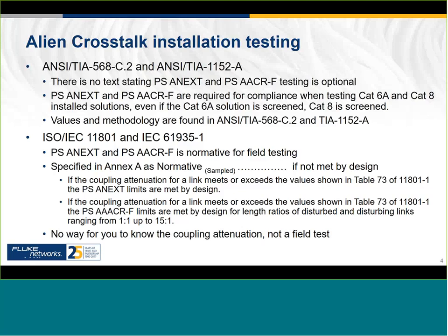One thing to point out though is in the field you do not know what the coupling attenuation is. This is not a field test, so it's fairly hard to work that out. So have we met the limits on the table in 11801-1? You don't know from a field test, so you've got to rely on your vendor, or if you're not certain, you have to test.